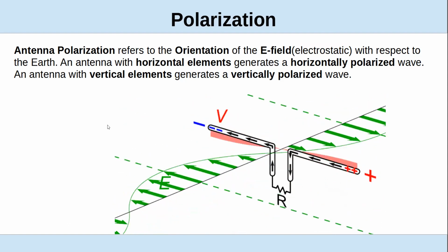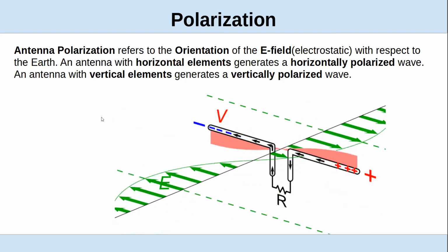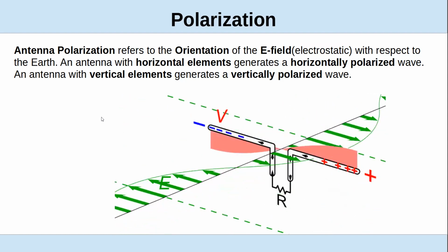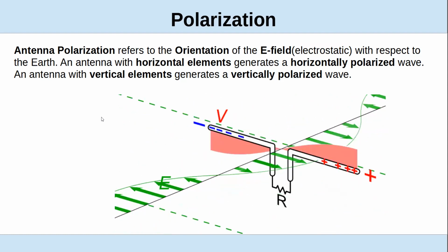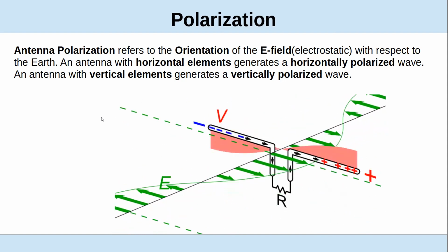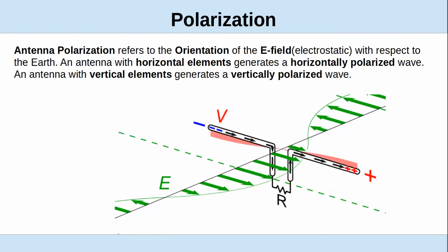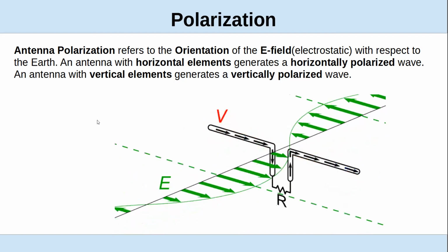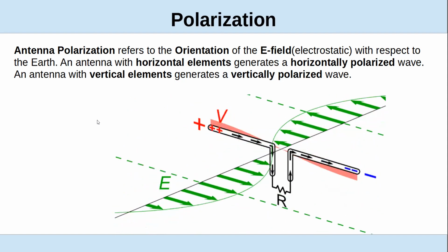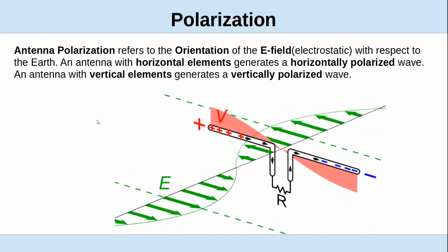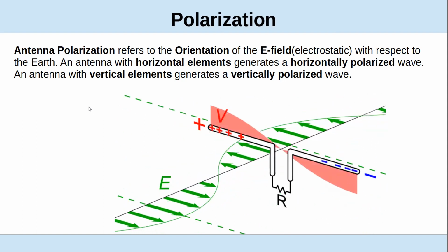Yeah, when you get to reflections, it changes. Anytime it's reflected off of things, it affects the polarization. And then, of course, when you've got a satellite that's rotating, it's changing vertical, horizontal. So a lot of times for satellite antennas, they'll have crossed Yagis so they can receive it either way.